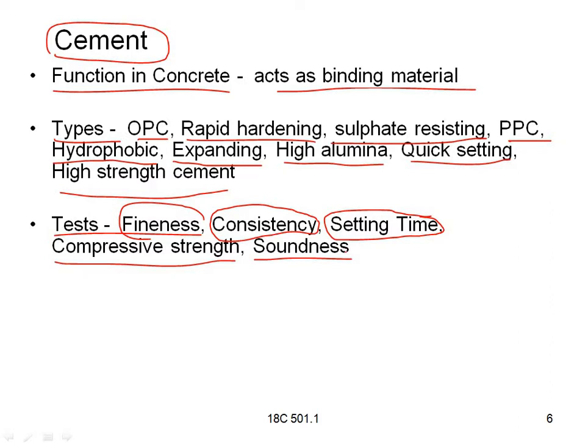And compressive strength of cement. The compressive strength of cement will be known when concrete is made up into cubes. Those we will call cement cubes. The cube size will be 15 by 15 by 15 centimeters. This is the standard size of the concrete cubes.